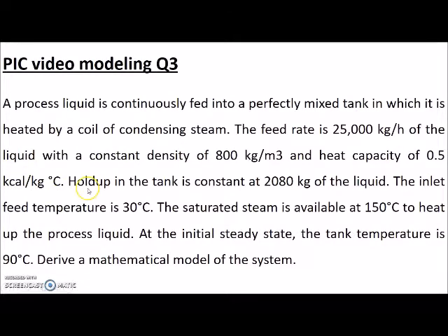They also state that the holdup in the tank is constant at 2080 kg of the liquid. Now they state the conditions: the inlet feed temperature is 30 degrees Celsius, whereas the saturated steam is 150 degrees Celsius to heat up the processed liquid. At the initial steady state, the tank temperature is 90 degrees Celsius. So I have to derive a mathematical model of the system.